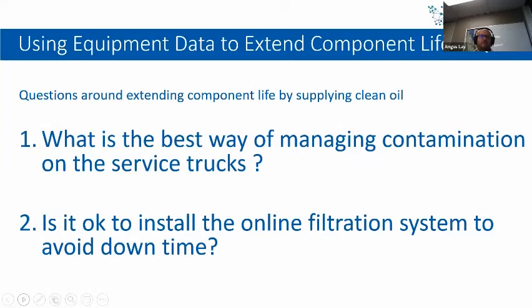They don't necessarily have the micron rating to remove the very fine particulates, which can be detrimental to the components on a hydraulic system, pumps and valve bodies and so on. So absolutely not a problem at all.